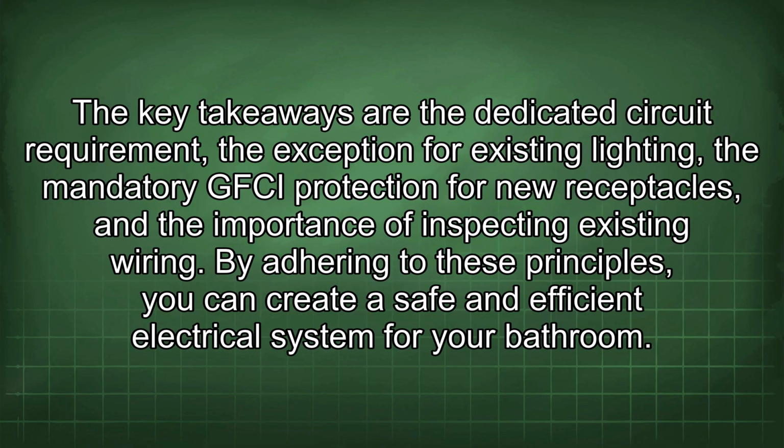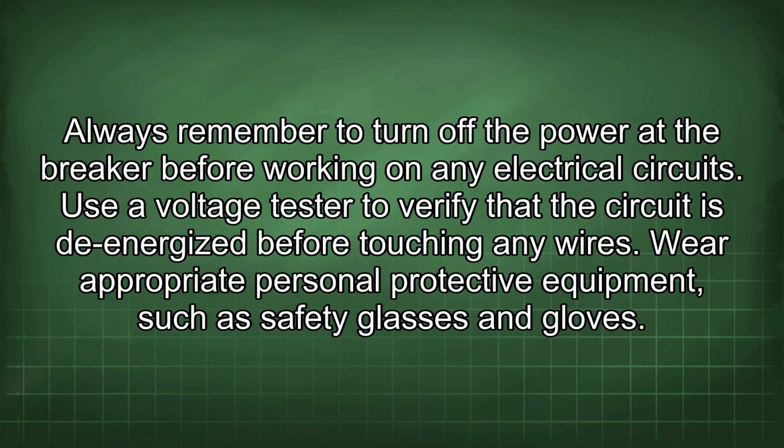The key takeaways are the dedicated circuit requirement, the exception for existing lighting, the mandatory GFCI protection for new receptacles, and the importance of inspecting existing wiring. By adhering to these principles, you can create a safe and efficient electrical system for your bathroom. Always remember to turn off the power at the breaker before working on any electrical circuits.